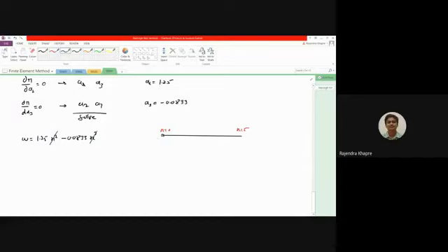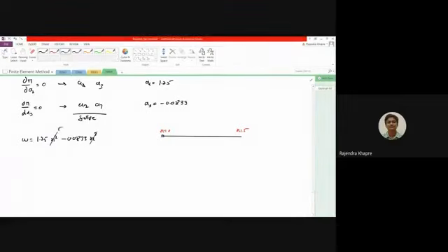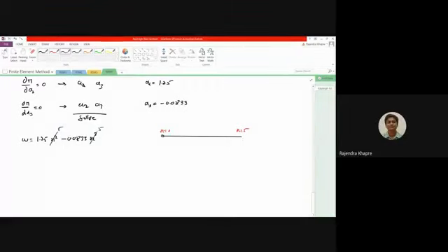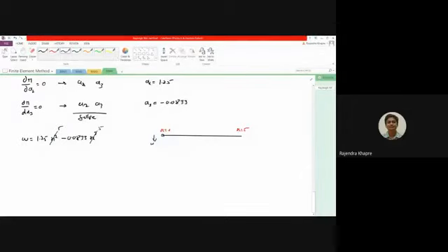Now let us substitute x equals 5. If you substitute x equals 5 here and here also, can somebody tell me how much is the deformation value, please? 20.8375. Is this negative or positive? Positive. Positive means, remember, we have assumed the w direction like this. So this is 20.8375, the deformation at the free end.